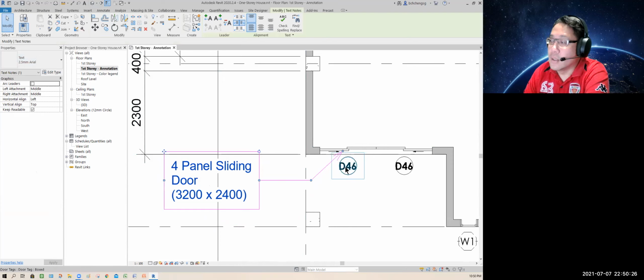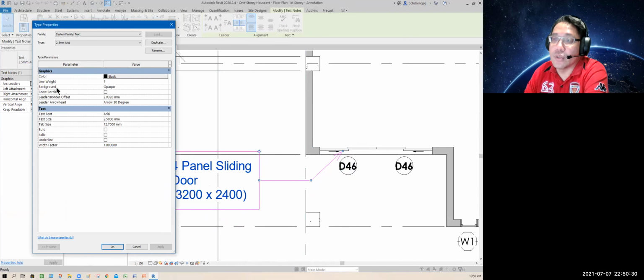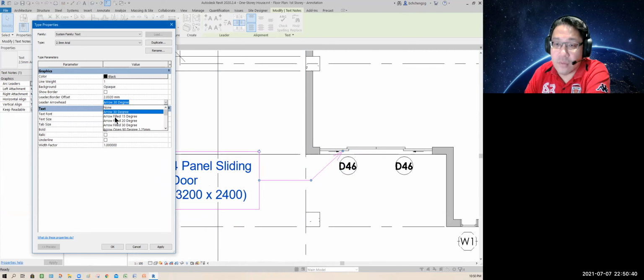Smaller. Yeah, looks nicer. Arrowhead changes are under edit type, which is leader head. When it says arrow 30°, normally this type is skeleton, unless you see the word fill. Okay, so 50 is a bit odd. 20 is good. 30 ugly.